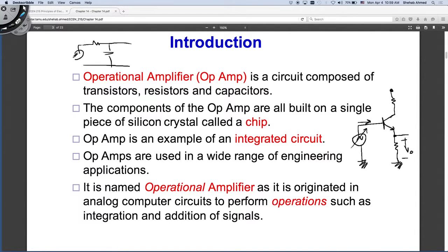Let's say the output of our sensor is not a continuous 1 volt or 3 volts. Let's say this sensor provides an AC signal output with a certain frequency. What this low-pass filter does is allow the low frequency to pass. So as soon as you see low frequency, there will be an output voltage across here, and I can turn on my motor.